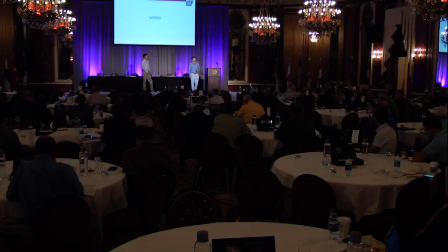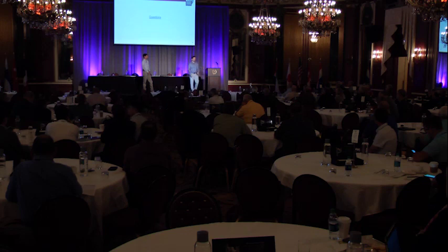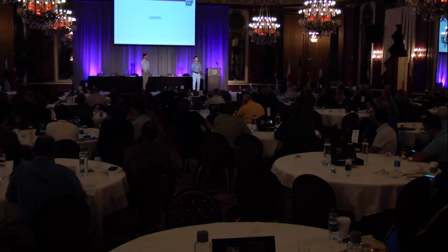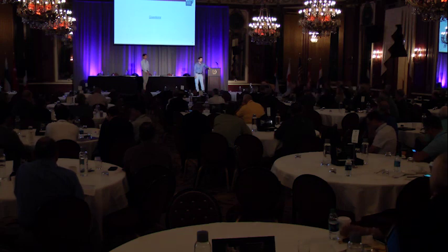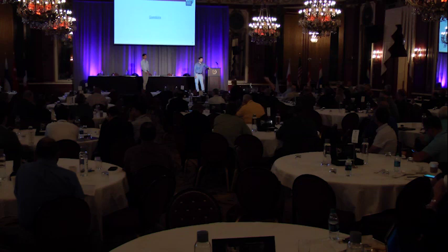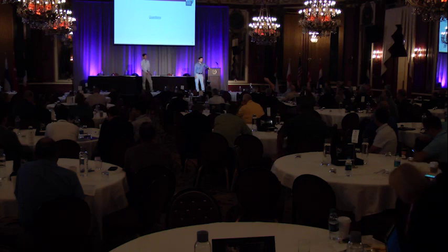Yeah, I mean, that's an unfortunate situation, but a lot of times, hopefully, with us reviewing the plans, with the engineer of record reviewing, and someone catches it, in some situations that does happen. Ideally, though, when we put together design, we will look and see if there's anything specifying a splice. The worst case situation is where there are no splices specified. So, if you guys are out in the field and you notice something, it's always good to get back in contact with us, because we don't always see everything either. There's a lot of buildings that aren't drawn. So really, the engineer should be out taking a look. I really think that the shoring contractor can be the last line of defense and notice something before they start doing the demolition. No, agree.